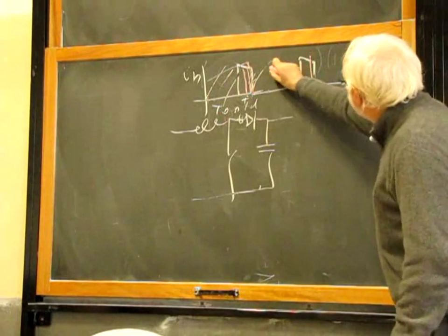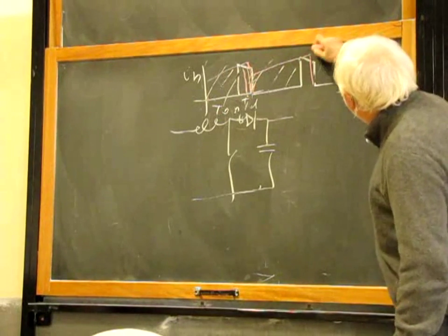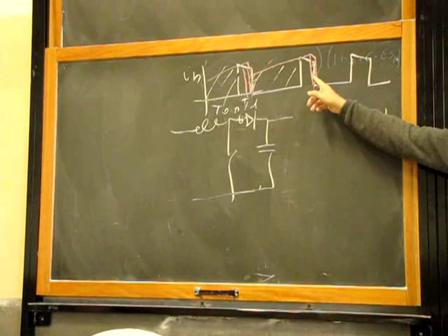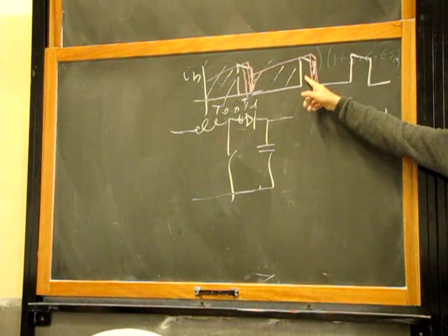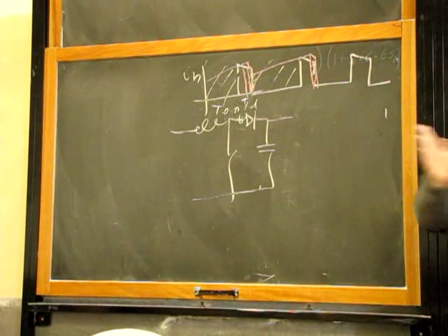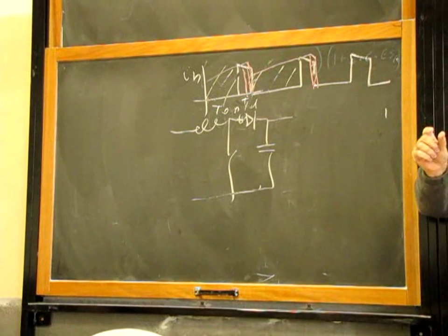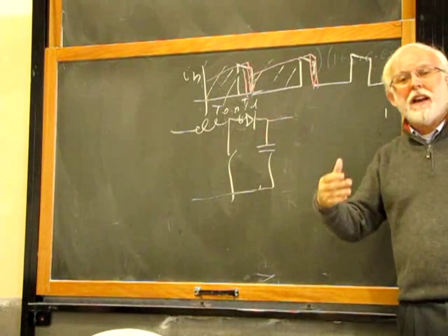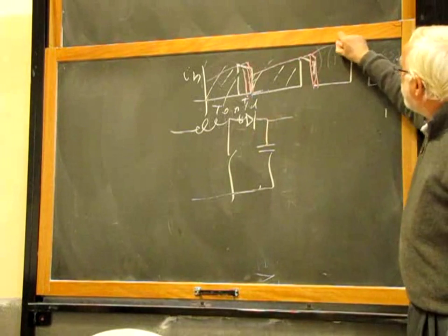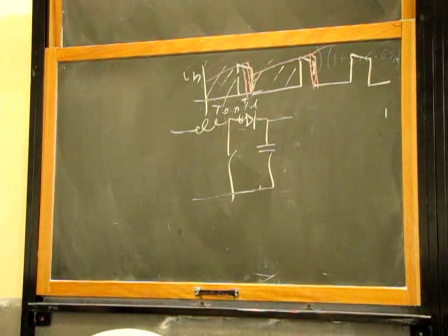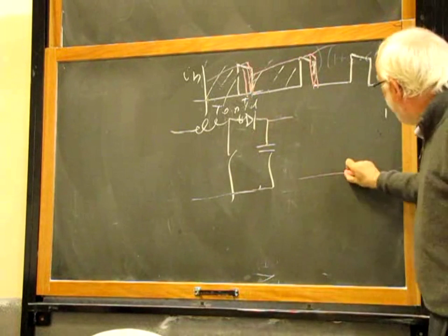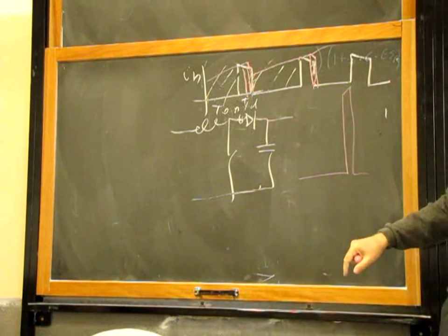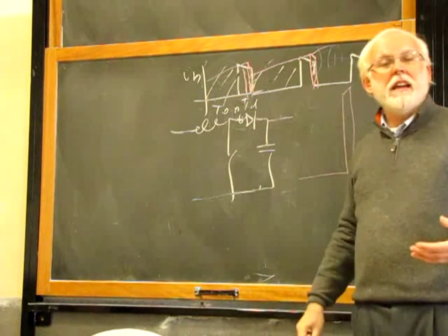If this is your output current, you see that the area of the output current, the red output current, is far less than the white output current. So the very moment you increase the duty cycle, you decrease 1 minus D. So you have less time to transfer energy to the output. Then, if you are patient enough, if you wait for some time, the inductor current will eventually climb up, and you will have something like this, very narrow, high pulses. But before getting there, you need many cycles because the inductor current increases slowly.